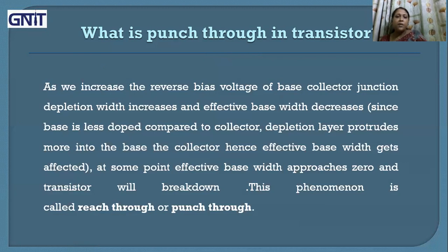Hence, effective base width gets affected. At some point of time, base width approaches 0 and transistor will break down. This phenomenon is called punch through or reach through.